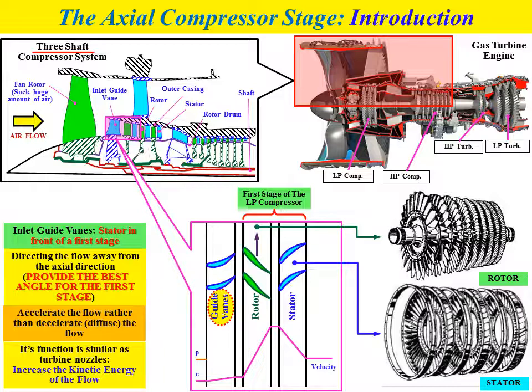But if you look at the pressure profile, in the guide vane the pressure will slightly decrease. In the rotor, the pressure increases, and in the stator, the pressure will increase more compared to the pressure increase in the rotor, because the function of the compressor is to increase the air pressure.